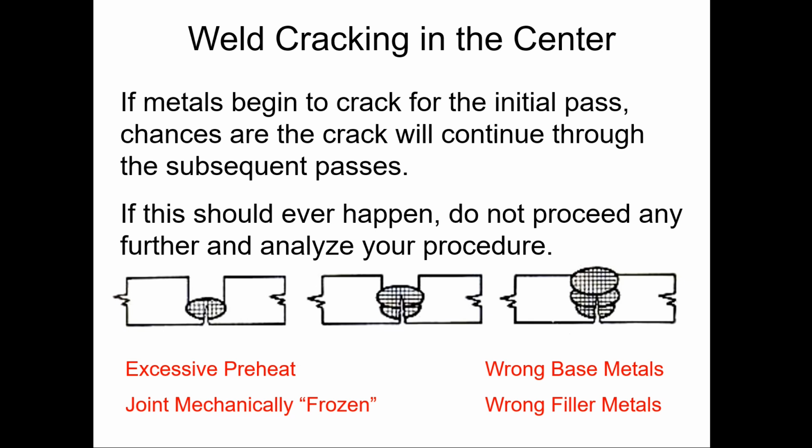Never start messing around thinking, if I just keep going, if I just keep trying it, it'll start to work. When you see this happening, it's highly likely that your base metal is contaminating your weld metal. We need to look at it all again. We need to look at what's going on if you ended up with a crack like this.